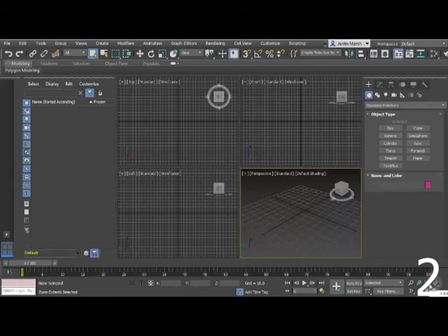So we're going to talk about some navigation hotkeys, but you can also access those navigation controls by clicking down here. As we move over to our left, on the left side, this is our Scene Explorer. And this is where we're going to be able to see the different objects in our scene listed in sort of a hierarchy. So once we start to bring in lots of things into our scene, kind of a spreadsheet that we can look at all the different objects, could be geometry, again, lights, cameras, whatever it is, we'll be able to see it in here. We'll be able to filter what it is that we're looking at. If we happen to have a bunch of stuff in our scene and we need to kind of pare that down, we can do that in our Scene Explorer.